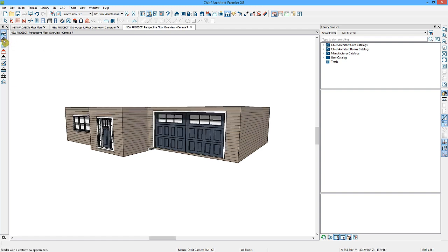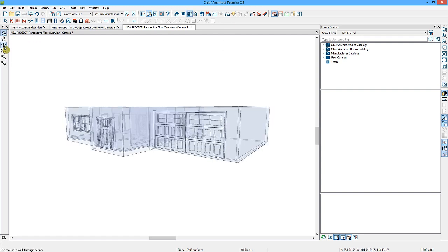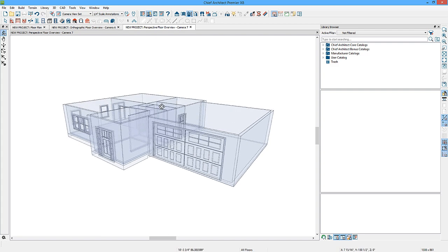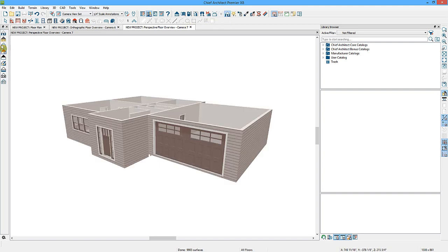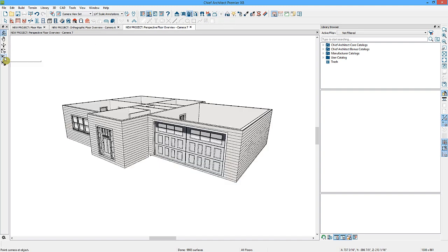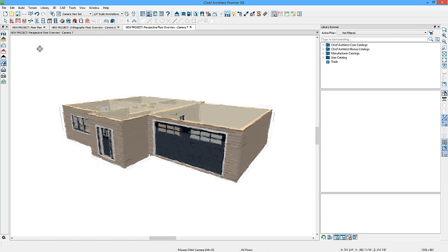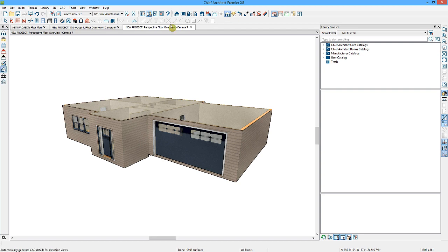If you go to the vector view render technique, it will see the color and pattern properties of the materials. You also have others, like the glass house. This will render all of the materials as transparent. You also have duotone, as well as technical illustration, and the paint render technique, and the watercolor render technique. You also have one called line drawing.